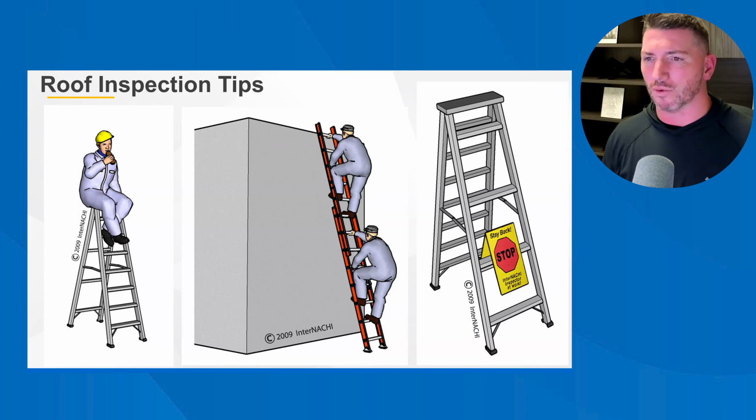One thing we'll touch on in a little while is the pipe boots or pipe vents, depending on what people call them. They are only designed by nature to last, I'd say, 5 to 7 years. Now, do they last 20 sometimes? All the time, no problem.